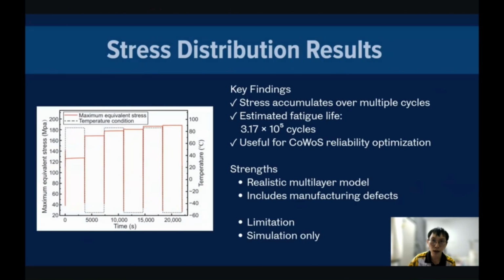Based on the simulation result, the estimated fatigue life of the TSV structures is approximately 317,000 cycles. Therefore, a strength of this paper is that it includes realistic interposer layers and manufacturing defects, making the result more representative of the actual CoWoS packages.